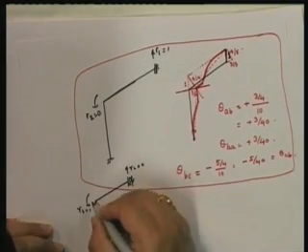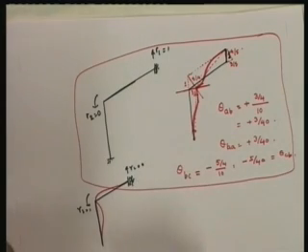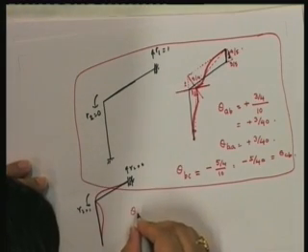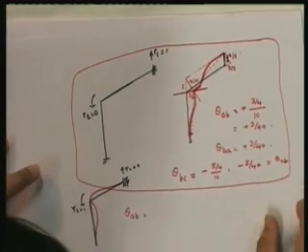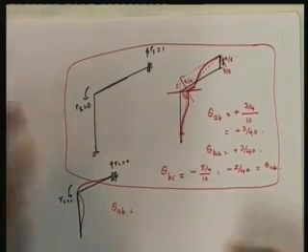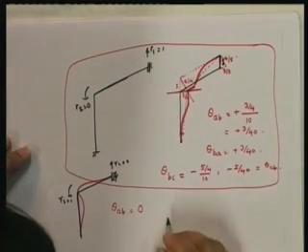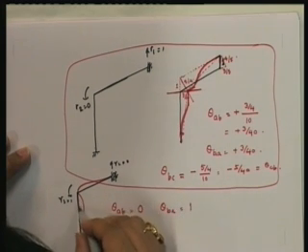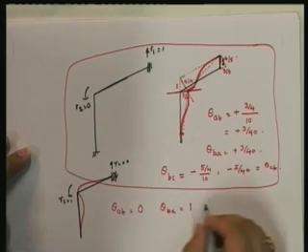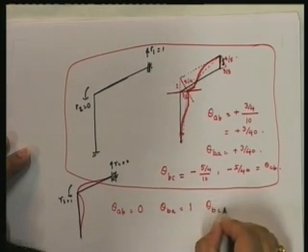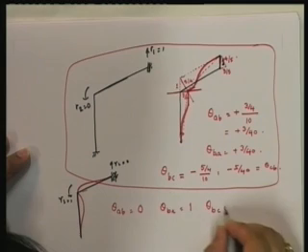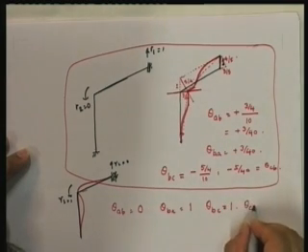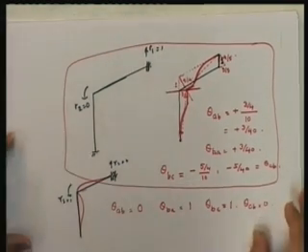It's going to be this, and if you put this, then what do we get as theta AB? Theta AB is equal to 0. Theta BA is equal to plus 1 from the chord to the tangent, that's anticlockwise. Theta BC similarly from the chord to the tangent 1. Theta CB is equal to 0.